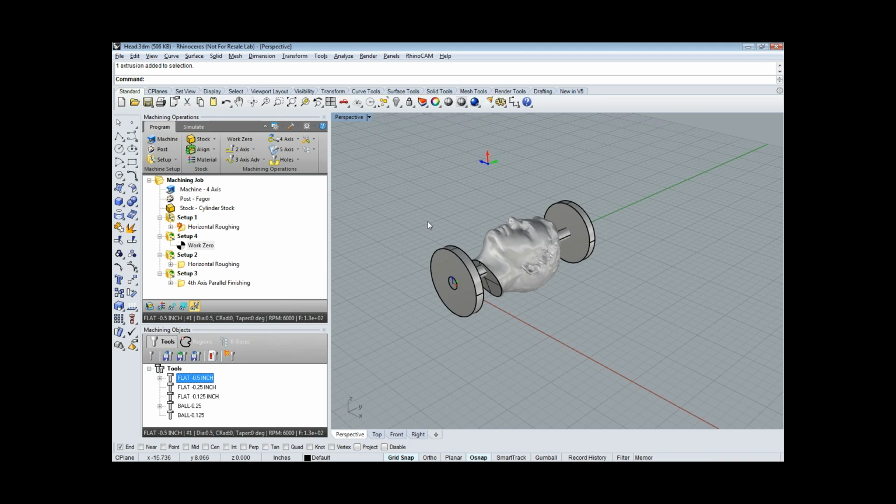Now, if it's going to be a 3-axis operation, the user can actually define the tool in RhinoCAM with the actual tool diameter by modifying the tool and then just regenerating the tool paths. Alrighty, great. Could I add something to that? Sure, please go ahead, Scott.